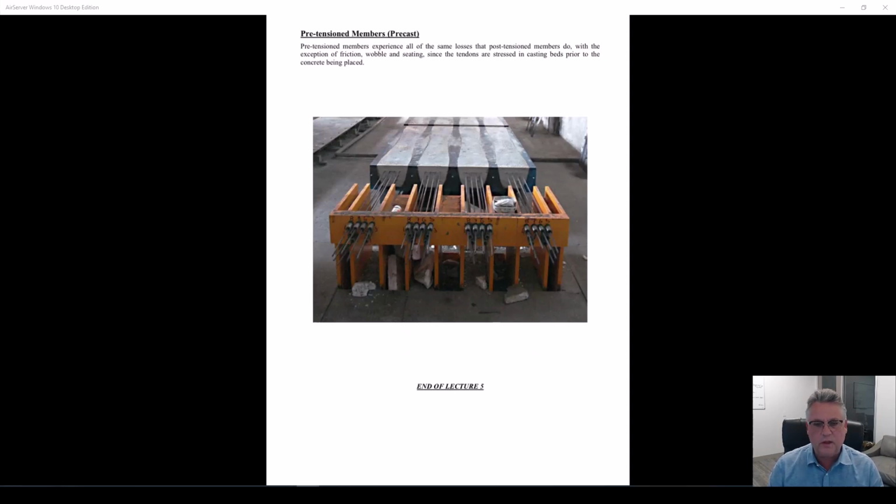I will give you something that violates the ACI flexural stress somewhere in the beam. Then I'm going to give you 2 methods of reducing something. First, it will be the drape, and secondly, it will be the number of tendons in one of the bays. And that reduction will actually solve the problem. So I'm telling you what the answer is in homework number 3. So don't spend so much of your time worrying about just getting the numbers right. I've told you what the answer should be. So if you're not getting those answers, there's probably a problem.